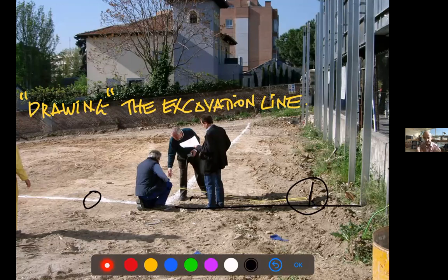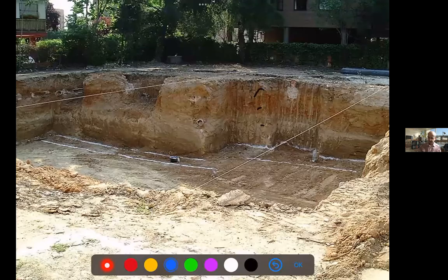So in this case, the millimeter dimensioning is totally meaningless. So once we excavate, you can see there's no precision there. If you're familiar, you can see the difference between layers, right? So this is like a terrible land you cannot use. This is the plantation one. This is quite okay, and this is the best part. So actually, it's what we call the quaternary geological times. This is tertiary, so it's like quite a few million years old. And this is the one which is proper for the foundation, right? You see all pipes, all remaining from all constructions, and those strings are the structural axis, right?